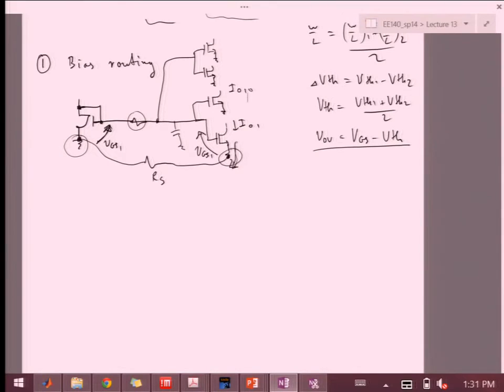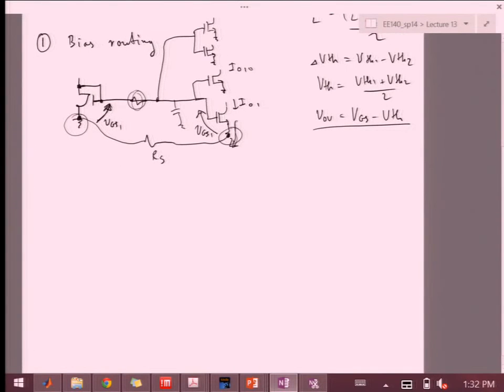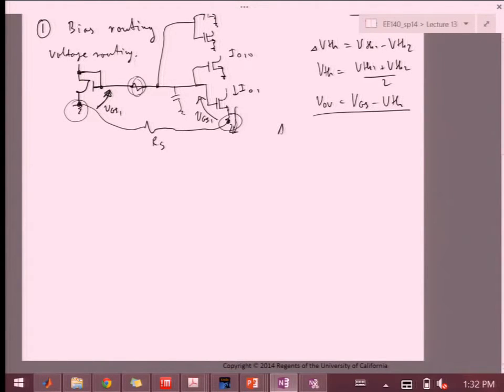So in order to avoid these issues, you never do this type of routing scheme globally, where the length of these wires is very big. You do it locally, where maybe you want to distribute to many places, a dozen little branches, but you use this one wire locally. And then you make sure that all these grounds are very closely, tightly coupled. So this is voltage distribution. Okay. So advantages would be here.